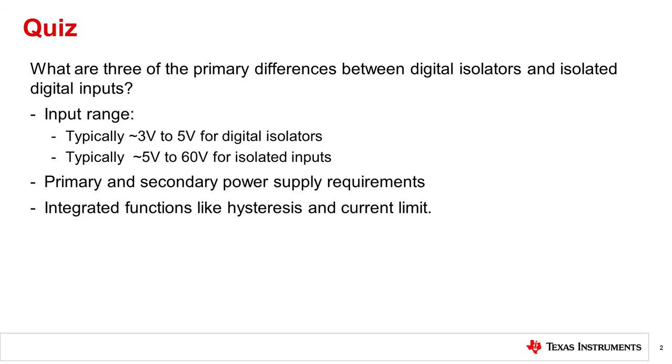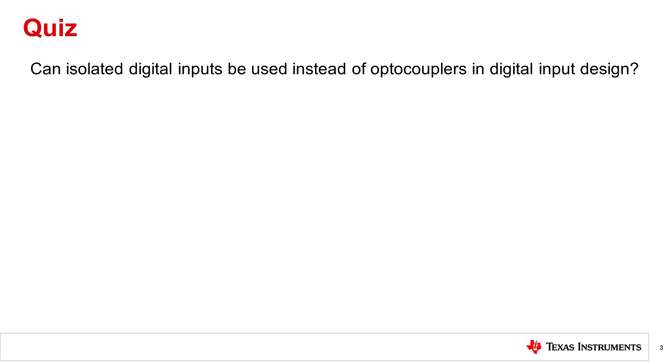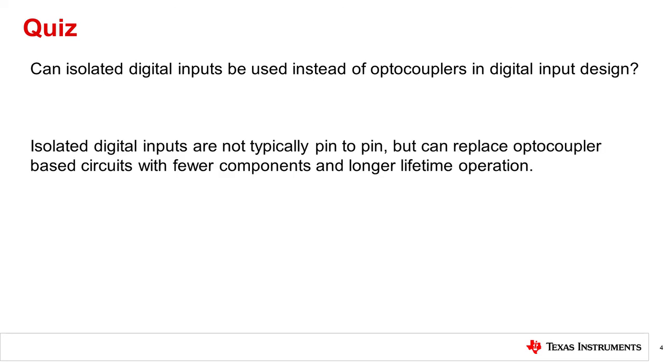Quiz question number 2. Can isolated digital inputs be used instead of optocouplers in digital input design? Yes, isolated digital inputs are not typically pin-to-pin with optocouplers, but they can replace optocoupler-based circuits with fewer components and longer lifetime operation.